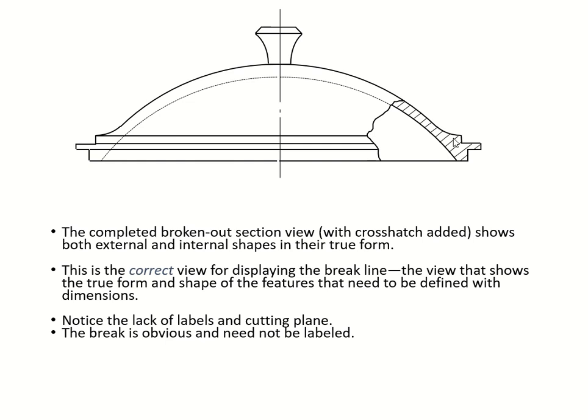We can see our cross hatches here, all of it. They are equally spaced to each other, at a consistent angle, yeah. So make sure you draw this with a ruler and keep the consistent angle, please. We're not using our cutting plane label, yeah, because we break it.